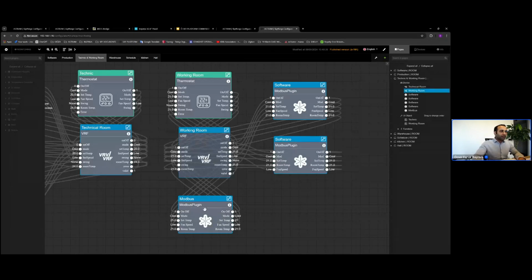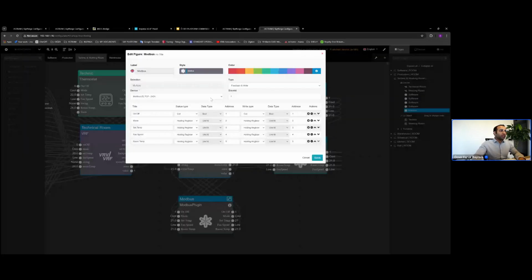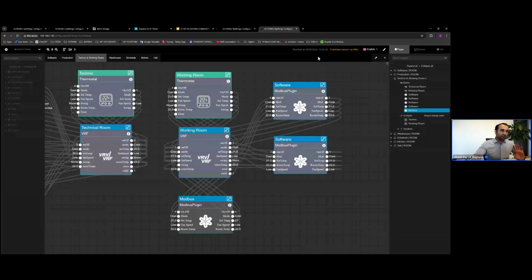As you can see, this is the slave device. I have added the mini server's Modbus TCP object as slave and assigned the same register addresses randomly. I just need to select the correct data type, and the port is critical, the slave ID is critical, and the addresses and the data types. Everything is critical, so you must have all this information.